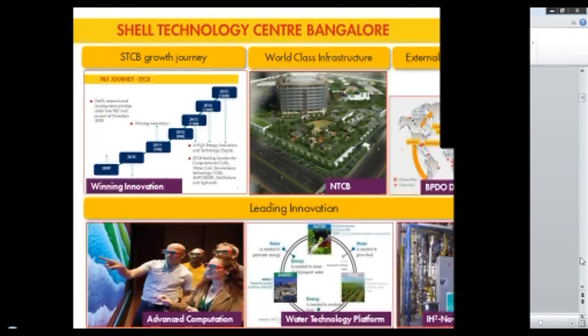Okay, so the first question there is from Shao In T, about the reed bed. Is reed bed being used to desalinate water in industries today? So the answer is yes, because I showed the example of Oman. There are more examples, but the reed bed is not desalinating the water. It's removing the hydrocarbons from the water. And frankly speaking, since some of the water will evaporate in the reed bed, the salinity levels will increase. So it's the alternative to deep well injection, and it's really a huge energy saver.